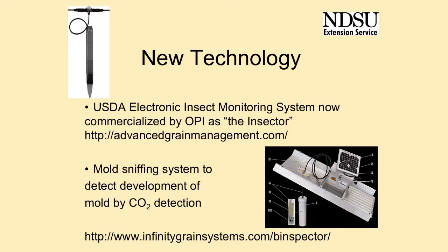Additional tools are now available to assist with managing the stored grain. One senses insects drawn to a probe, and the other measures the carbon dioxide level. Both insect infestations and grain spoilage produce carbon dioxide, so monitoring the concentration assists with detecting problems.